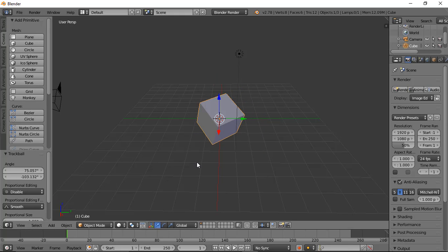And if I want to move it in Y axis, R plus Y, and it will move as per Y axis. Now to rotate a set number of degrees, for example you want to rotate it by 30 degrees, again press R with the degrees you want to rotate. Suppose I want to move it by 45 degrees, I'll press R then 45 and it moves by 45 degrees. You want to see it again? Then let us try it with 70 degrees. R plus 70 and it moves by 70 degrees. This is how we move it by degrees.